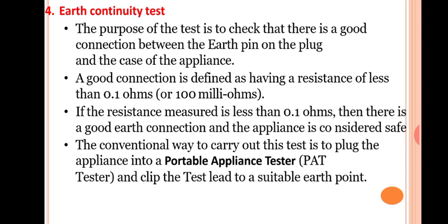This earth continuity test is mainly to see that there is continuity in the earthing. The earthing should not break. Once the earthing breaks, the leakage current will be circulated in the surface of the metal, and when you touch this metal, you will experience a shock.